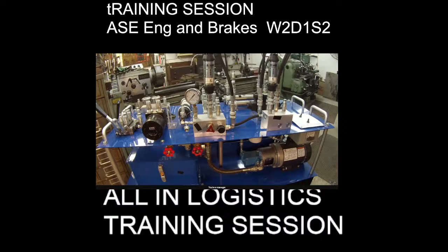The first one is flow makes it go. Flow is speed. If your component is speeding up or slowing down, that is a result of the flow that's coming out of your pump. Okay? So I'm going to turn this system on right here, and what it's going to show you is this pump is pumping right here 1.8 gallons per minute. And I'm not moving anything, still pumping fluid.